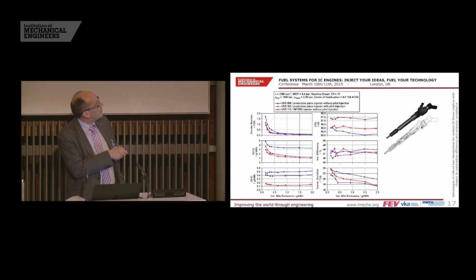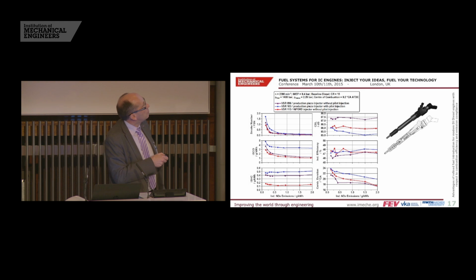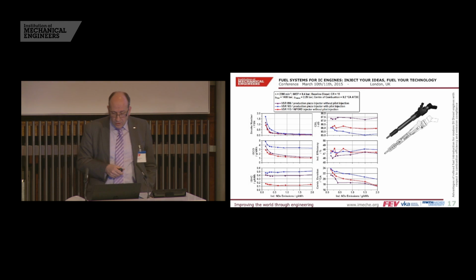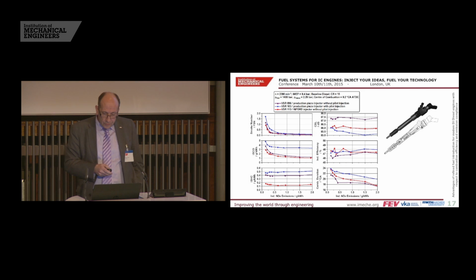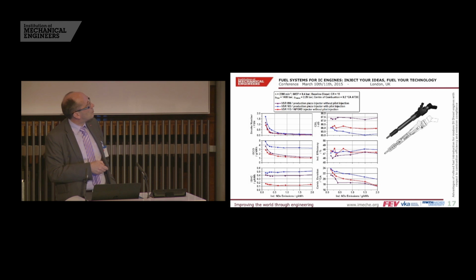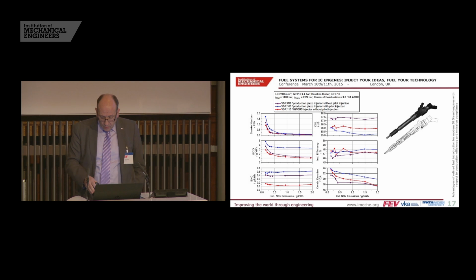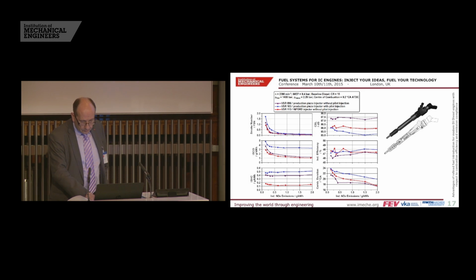Also, the same is true more or less in terms of indicated engine efficiency. Also here, the fast and rapid fuel introduction results in quite good combustion efficiency, which is more or less comparable with the situation of the pilot injection-assisted piezo injector. Combustion duration is, of course, then in between the 2 other counterparts.